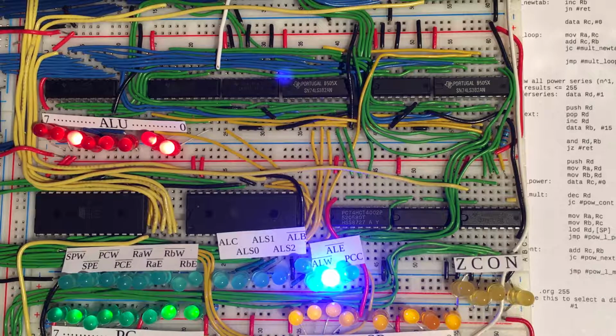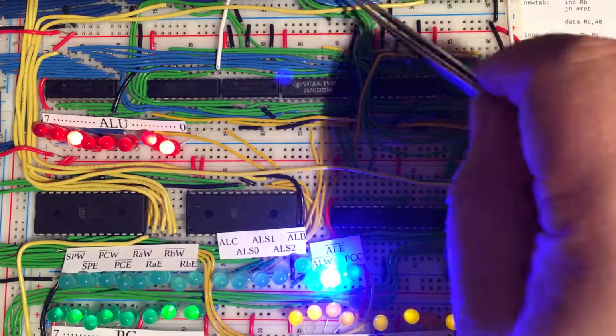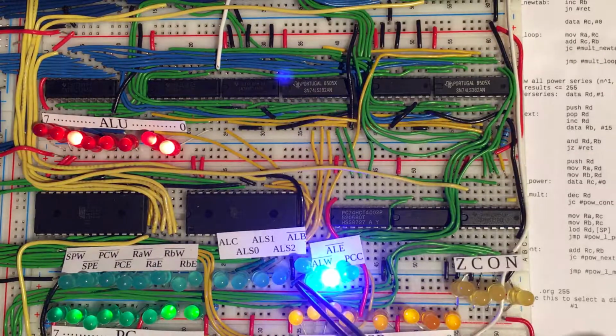And so the control logic has several signals with which it controls the ALU, and so 4 of those are going to determine the actual operation to be performed. We have another signal which tells the ALU what its second operand should be. First operand is always the contents of the bus, and so sometimes the second operand will be the actual contents of the B register, which come in through these green wires, and sometimes the contents will be a hard-coded value.